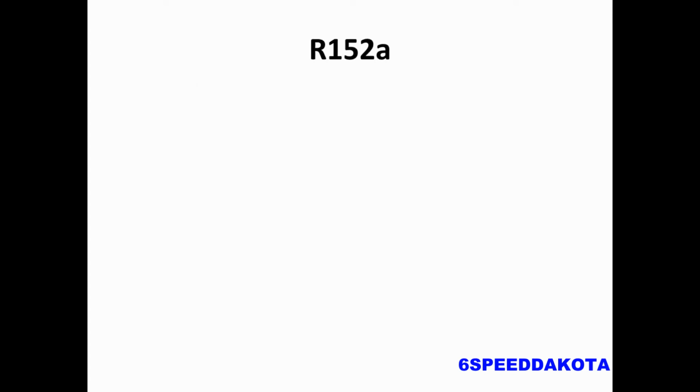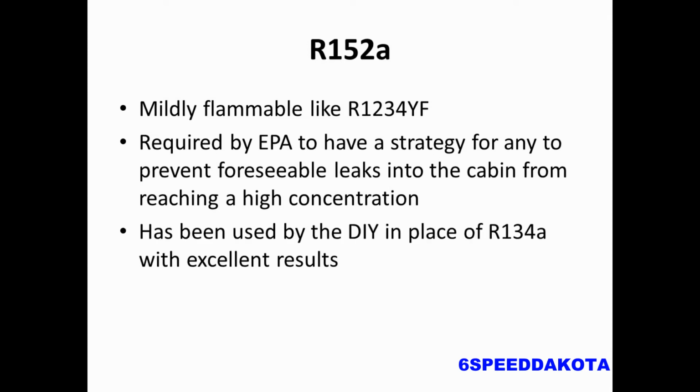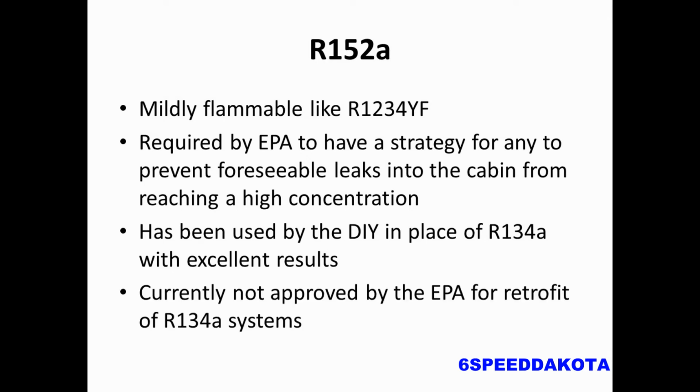R152A is also mildly flammable like R1234YF, and you are required by the EPA to have a strategy to detect any foreseeable leaks in the cabin. And if there's an issue, there has to be a strategy to prevent any buildup of refrigerant. It has been used by DIYers in place of R134A with decent results, but it's currently not approved for a retrofit of R134A systems.